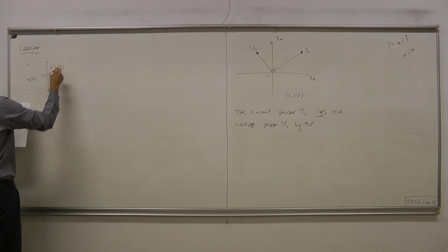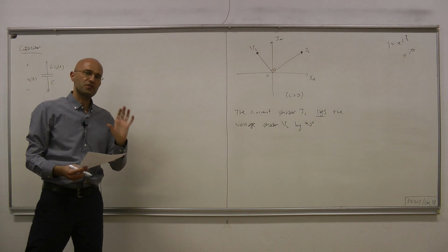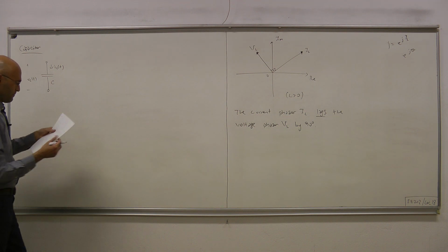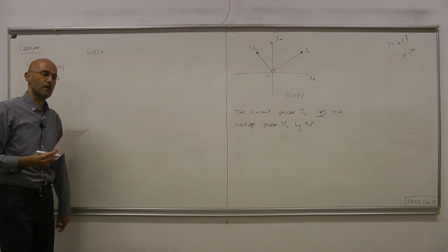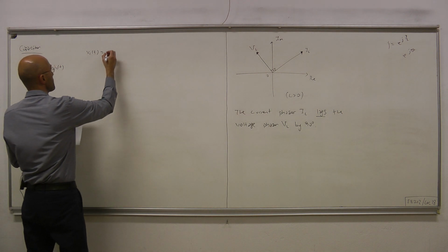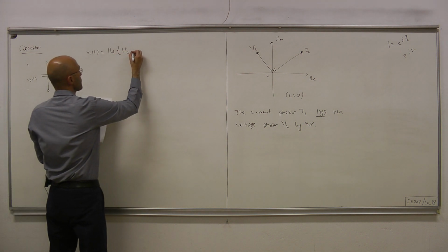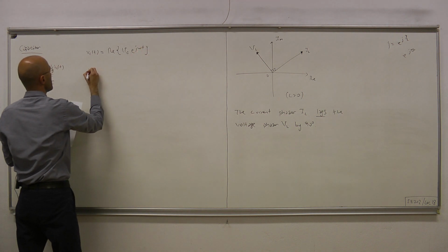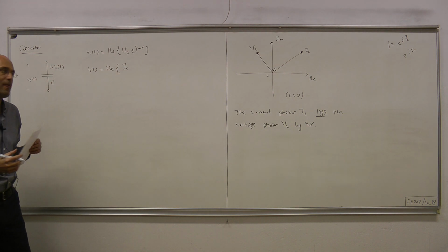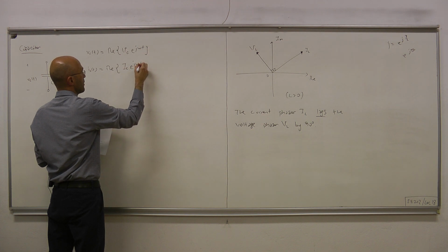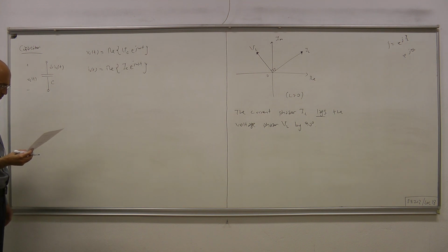This is IC(t). As before, we assume that this capacitor belongs to an LTI circuit that's in sinusoidal steady state. That allows us to express the capacitor voltage and the capacitor current through their phasors. Capital VC being the phasor of VC(t), and likewise capital IC being the phasor of IC(t), times e to the j omega t. Once again, omega is the frequency of operation.